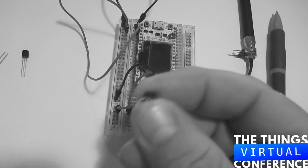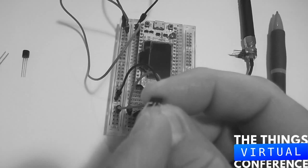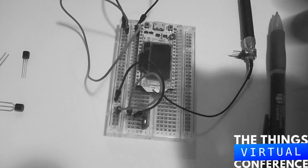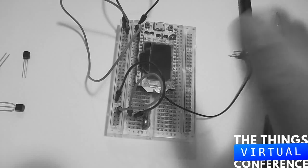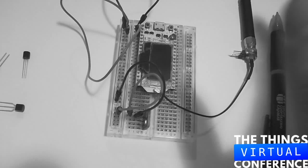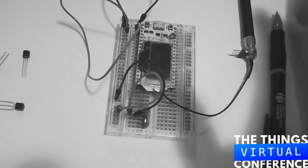So ground to the ground at the microcontroller, and VDD to the power, and the middle one, that is the one wire connection. And on many microcontrollers, you can decide which one you want to use for one wire. And I would say with this Heltec, use 17. That's one possibility. You can use 12 or 13, the pins or GPIOs.